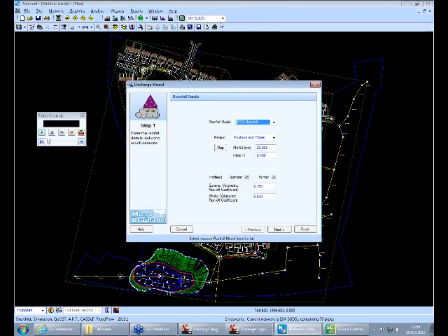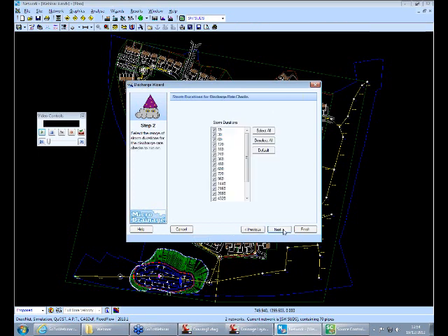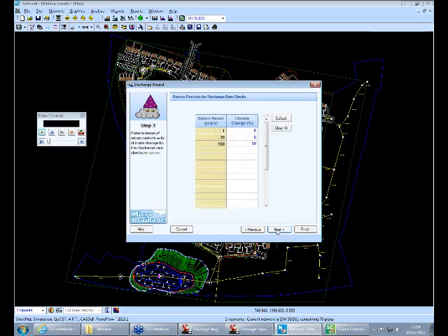notice in the top window I'm focusing on the surface water scheme that James has just earlier designed. I'll run the summer and winter profile storms and click on next. There are 5 steps to run through. I plan to run through all the different storm durations. So this ranges from 15 minutes up to 10,080 minutes. That's 7 days. Click on the next button.